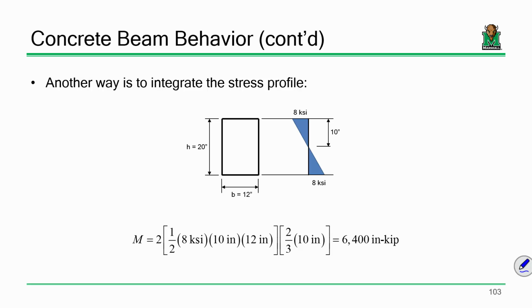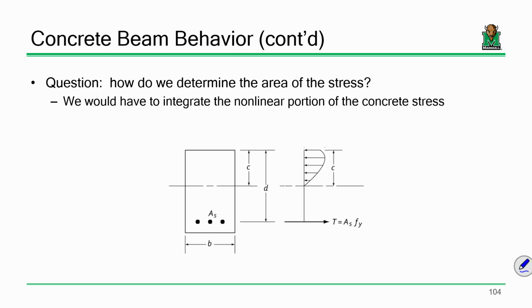So a calculation like this is very effective, okay? I asked you what bending moment would generate a stress of 8 KSI. So if I told you, here's this beam, it can only withstand 8 KSI, what's its maximum moment? This is an effective tool. Everybody okay with that? Now, it's effective for other reasons as well. This bending stress profile is assuming that the beam that we're looking at is behaving very linearly, right? Linear behavior, right? The problem is that concrete is not linear, okay? Let's go back a few slides.